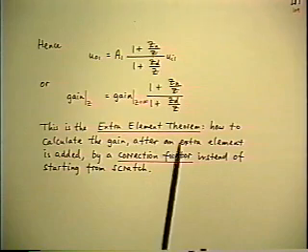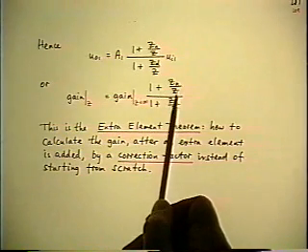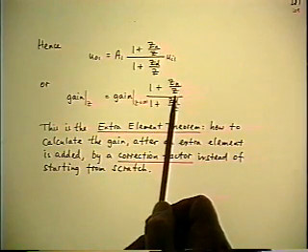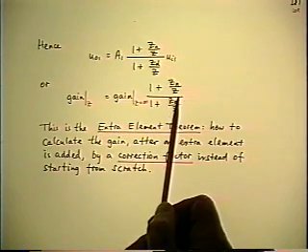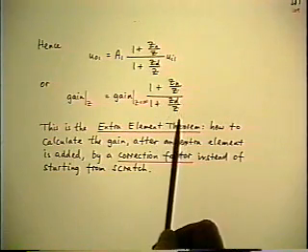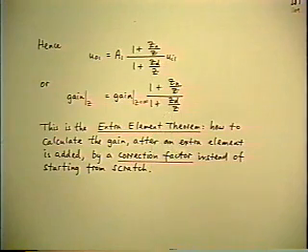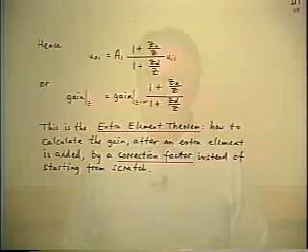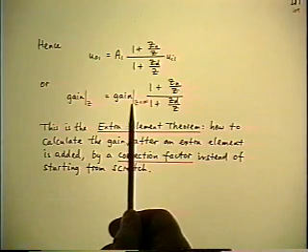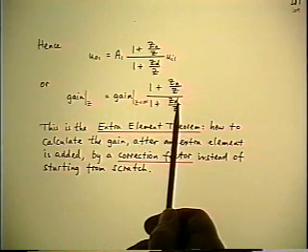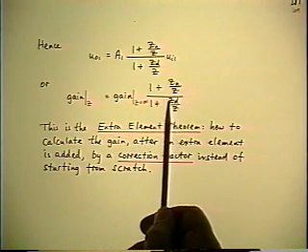And I emphasize again, the Zd and the Zn are calculated on the original box. And I very carefully, during the derivation, did that before I even mentioned the Z. In fact, the Z was the last thing that appeared. So all of the parameters in the formula, the original gain and the 2 driving point impedances, are properties of the original box.